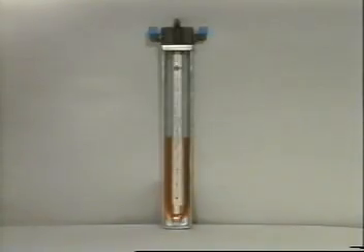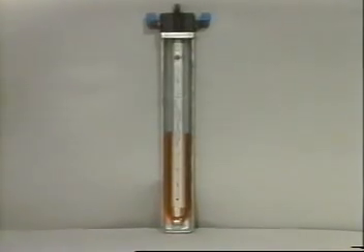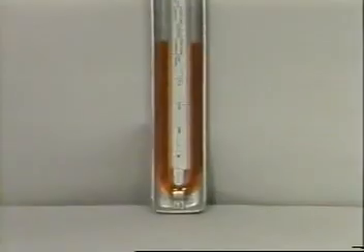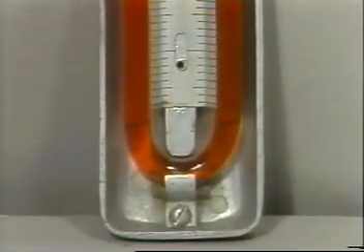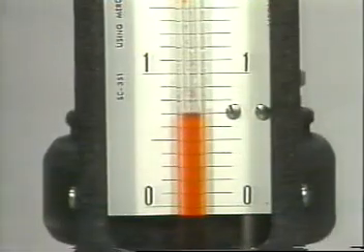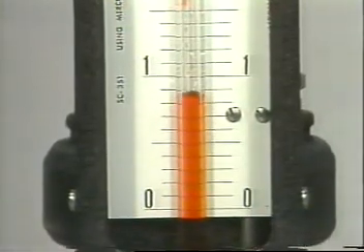Another way to measure pressure is to relate it to the hydrostatic head of a column of liquid. That's the principle at work in a manometer, such as this one. This manometer is a U-shaped tube containing a liquid. A graduated scale is used to indicate the height of the liquid in the tube. In this example, for demonstration purposes, the liquid used in the manometer is colored water. This well-type manometer has a single tube.